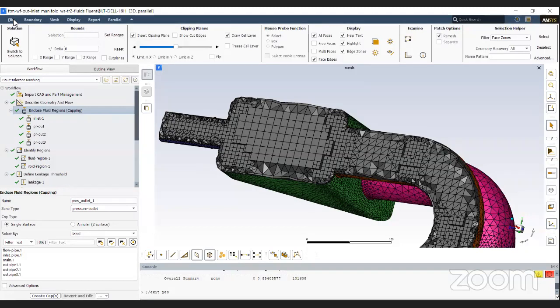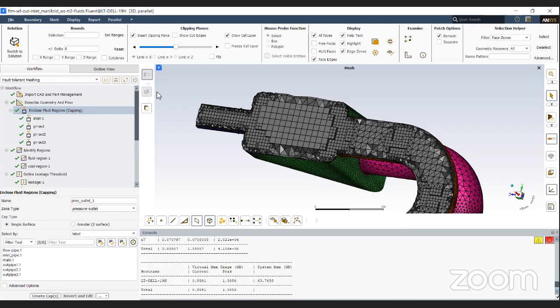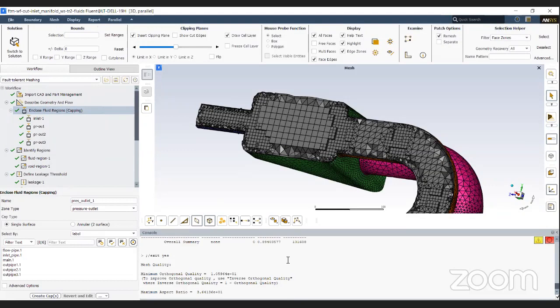Okay. And then one last question. For the interface here, we're looking at the Fluent Meshing interface. It's slightly different from Ansys Fluent, the solver. Are we able to see mesh quality here? Yes. So here you get a brief summary of the mesh quality. Usually I look at skewness and the orthogonal quality or the aspect ratio, but you could also just go here and check quality, and that would give you the same results.